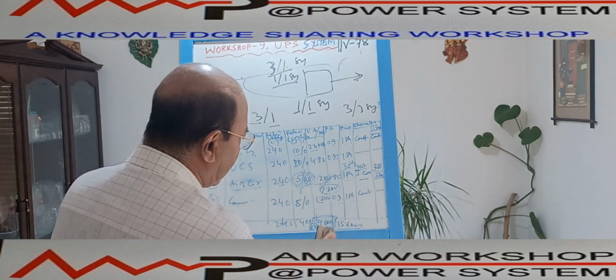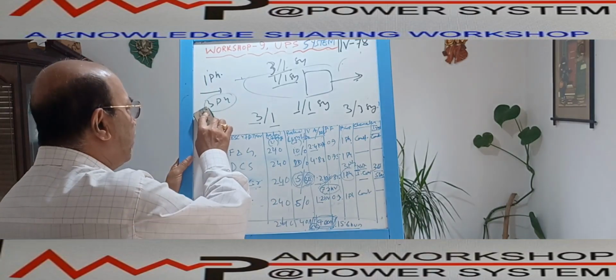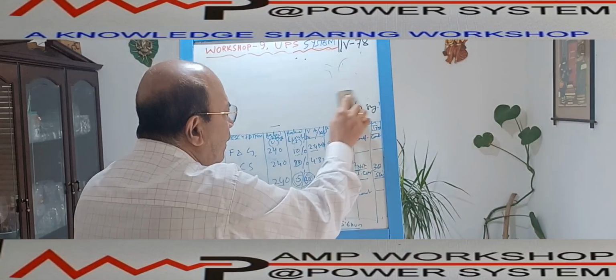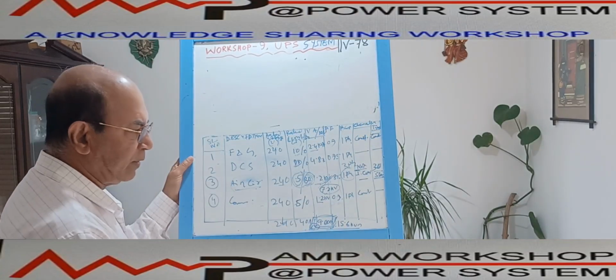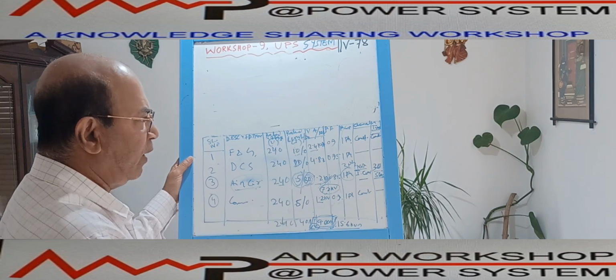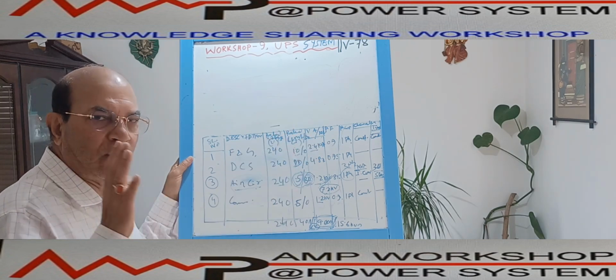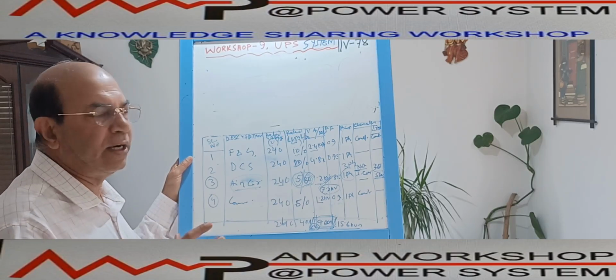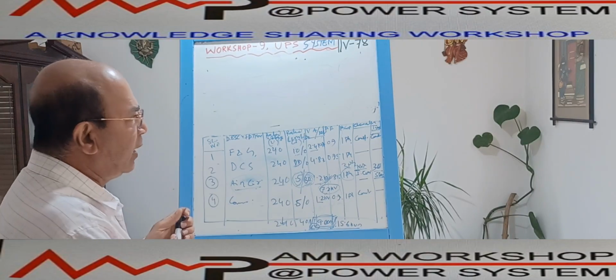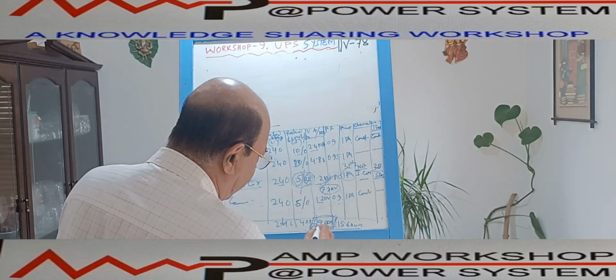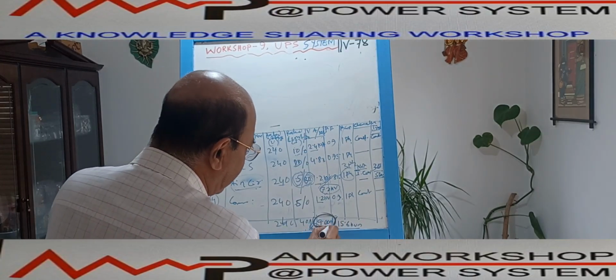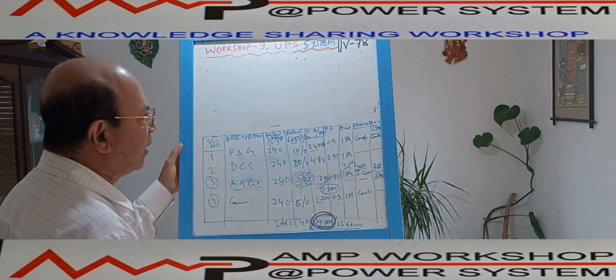Now, once the continuous kVA is decided, then we can calculate the UPS size. Suppose let us consider first all the current is a constant current, meaning there is no inrush or there is no dynamic current. All the current are steady state RMS value. In that case, suppose based on the full load, the steady state current is 9.6 kVA.